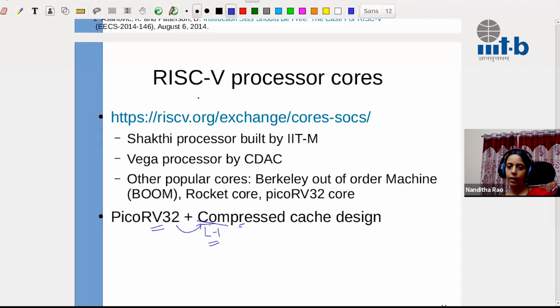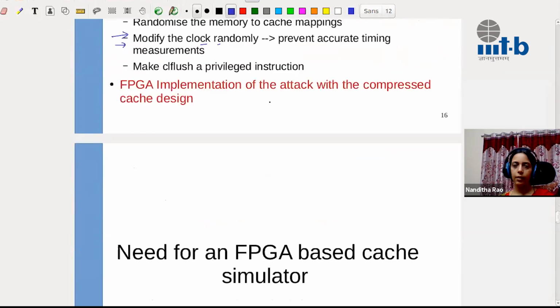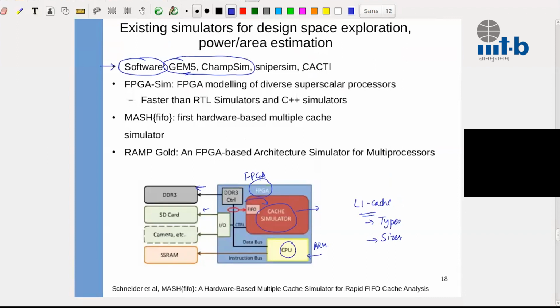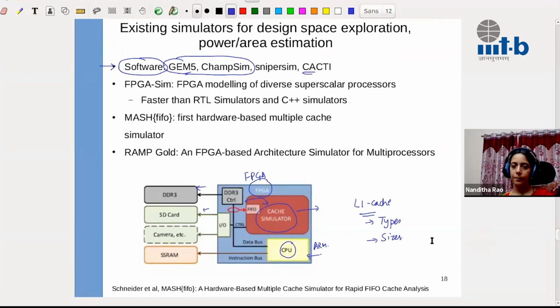There's one more question from Prasanna. Are lumped parameter cache models adequate for deep submicron? I think distributed models and more accurate models are required. The tool that I showed here, called Cacti, models the submicron level of details up to about 32 nanometers. They don't have anything smaller than that. Currently we are probably at 7 nanometer or 4 nanometer, and they don't have models which can model it right now.